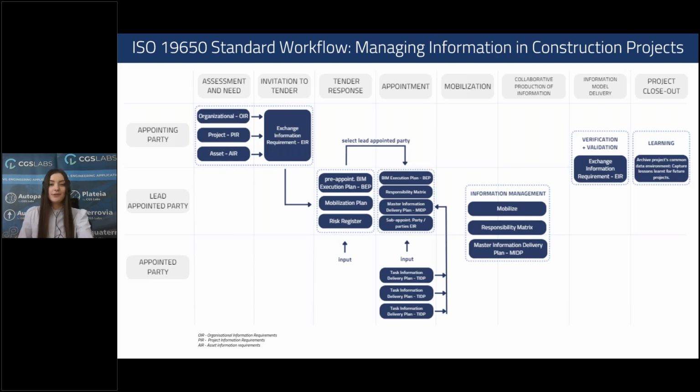project close out. The workflow begins with the appointing party, or the client, appointing an information manager. This manager is responsible for creating a group of documents that summarize the project's exchange information requirements. So the exchange information requirements document then becomes an invitation to tender.